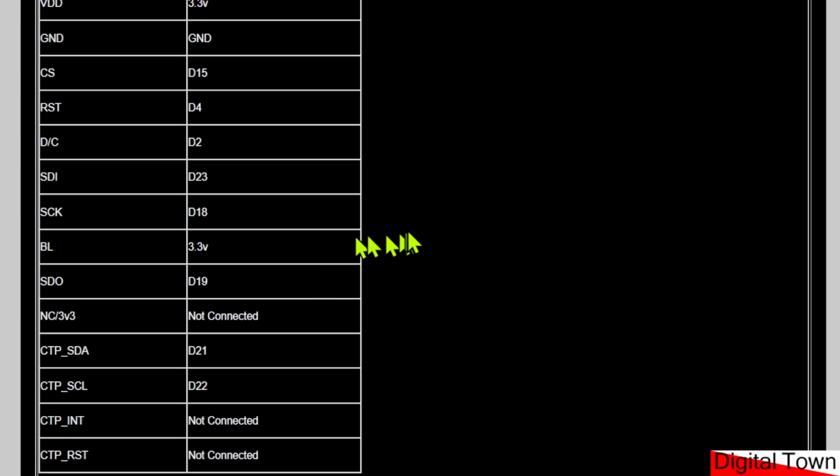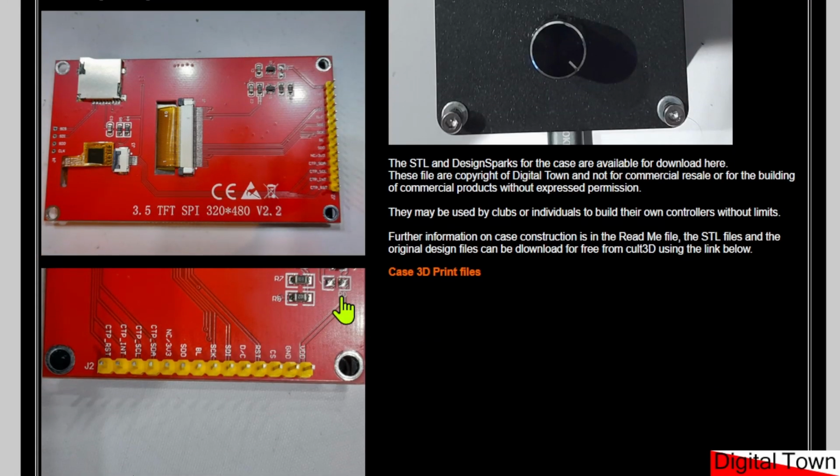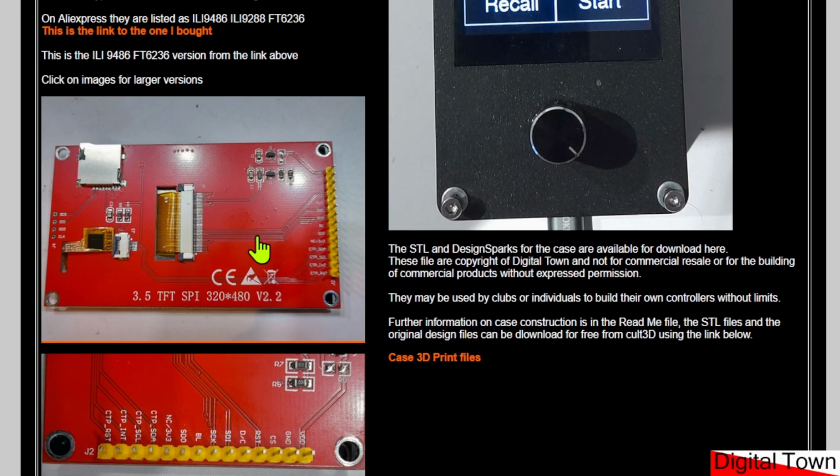These are the pinouts for the EEPROM. If you're using the EEPROM, you'll need to go to the EEPROM link. And one other thing, when you are buying the screens, make sure that you go for an ILI9486 with an FT6236 touch system. The FT6236 is the capacitive version of the screen. If you see a screen that has, if you like, a little probe that comes with it, that will be a resistive version, and don't get that one.